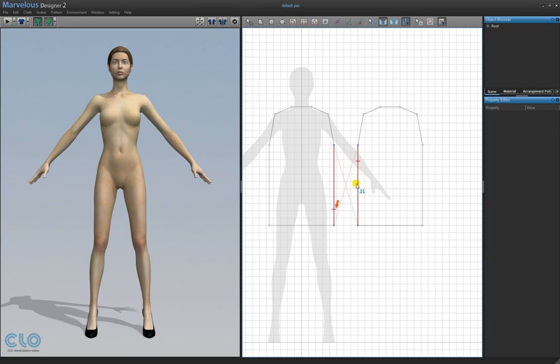This is because we have the mouse at the opposite end of the second line. Move the mouse over to the other end of the line and make sure the dotted lines are parallel, not crossed. When there are many seam line pairs, it may become difficult to tell if the dotted lines are parallel or crossed. In this case, you can also check the sewing notches that form along the seam lines to make sure they have been placed and matched correctly. Click the second seam line. Sew the rest of the seam lines in the same way.